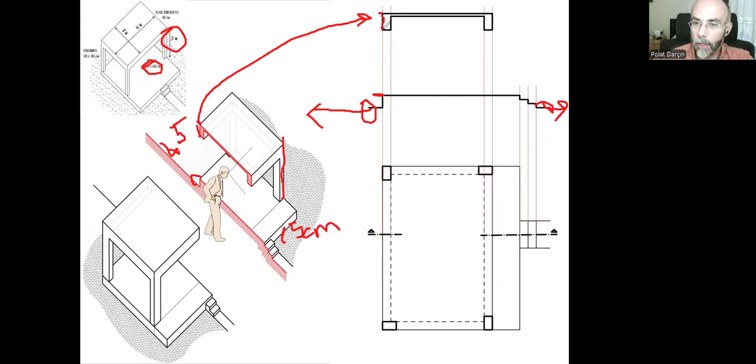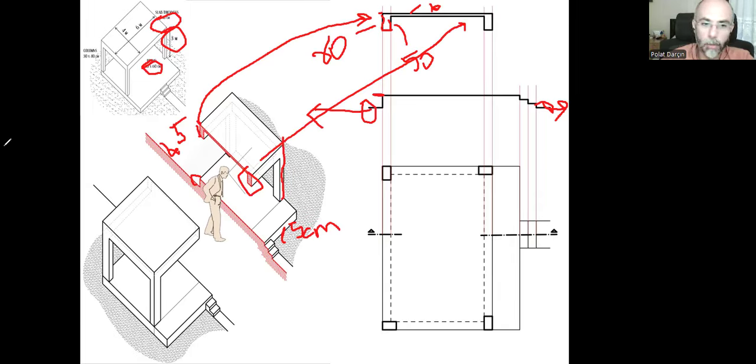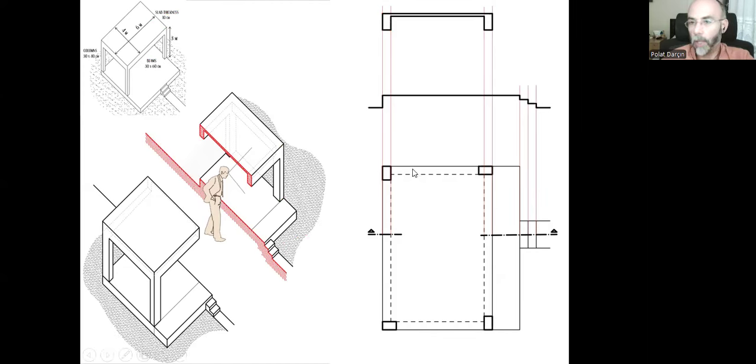And I have the thickness here. I can go 30 centimeters. I don't need to measure it one more time because it's already there. And go 50 centimeters upwards because of the slab thickness. There is this 10 centimeter thickness. So if this is 60 and this is 10, then I need to go 50 upwards in real sizes and create this floor slab with two beams. Do the same for this beam here, and that's it. These are all the cut surfaces of the building structure.